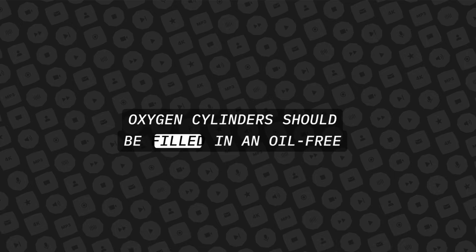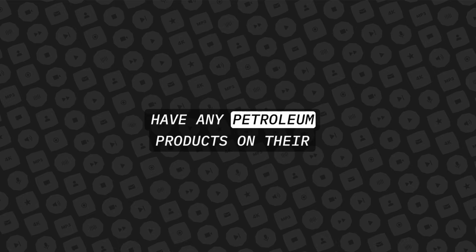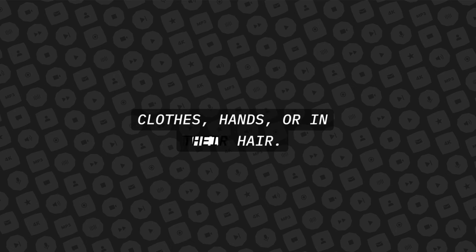Oxygen cylinders should be filled in an oil-free environment. The mechanic who fills the cylinders should not have any petroleum products on their clothes, hands, or in their hair.